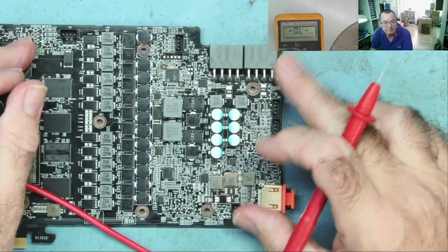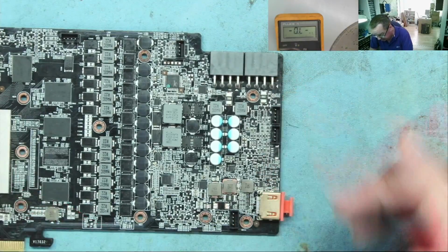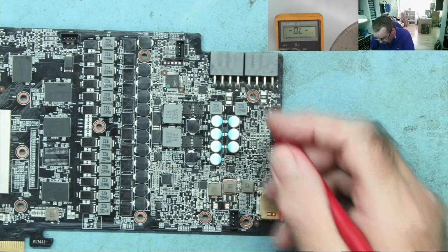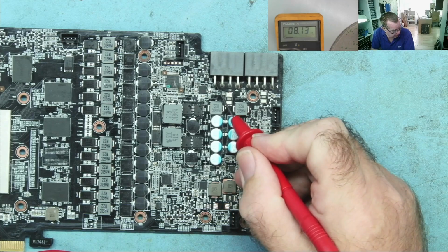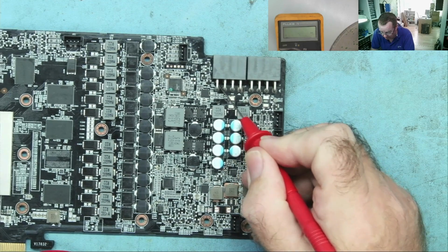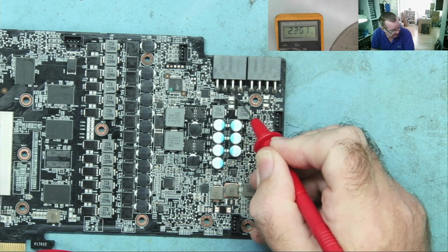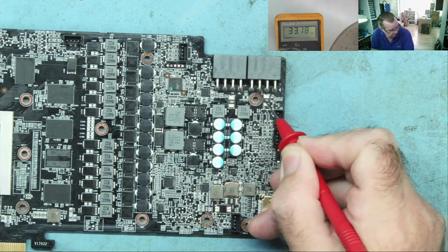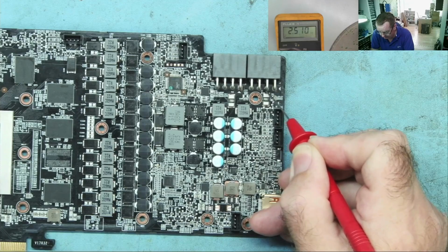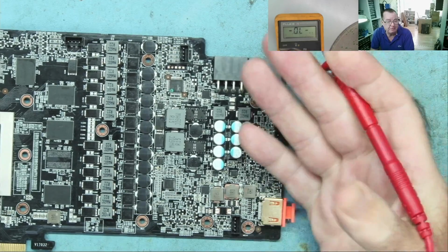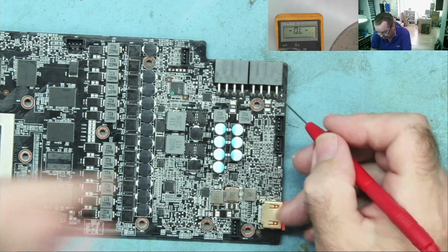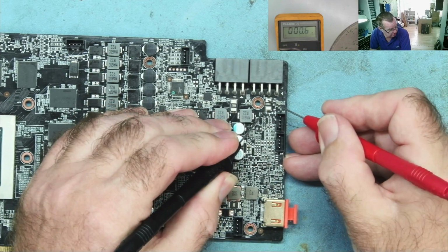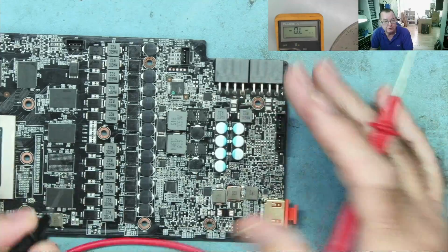We also have the 12 volts coming in here. What do we see? Well, that reads kilo ohms. Again, it's the kilo ohms. So there's no short here. Also, if we read something like kilo ohms, it pretty much tells us the fuse must be okay. Otherwise, we would read open circuit. Fuse is okay. So the fuse is fine on this.